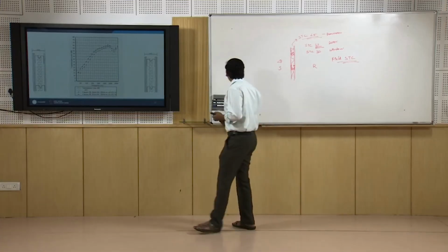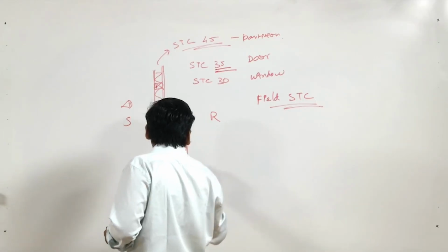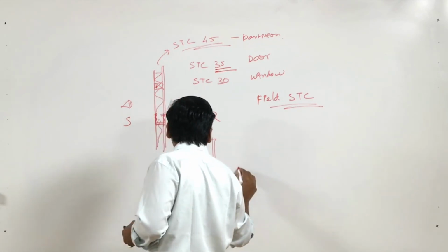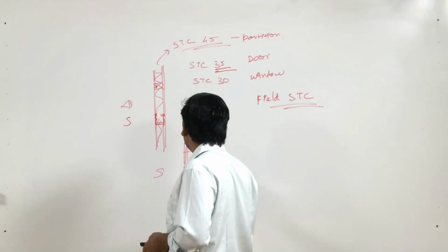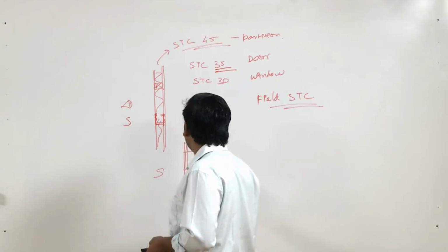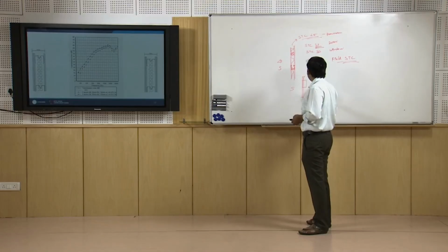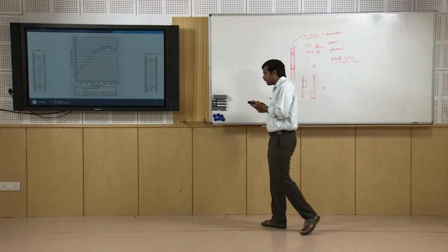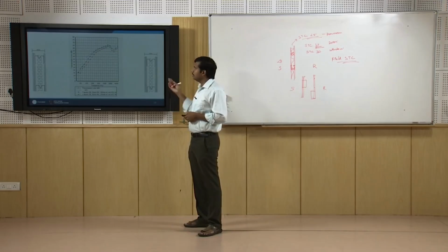Other common considerations: you have 2 panels, there is one board here, there is one more board here, this is a source room, this is a receiver room. If you are placing, say, switch boxes on both of these, do not place them side by side; it is advisable to place them in a staggered manner. Anything like staggering, some common, logical principles can be applied so that an effective STC can be attained.